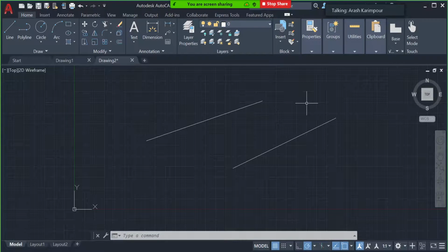How does it help me? It helps me change the properties of that layer altogether. For example, if I want to change the color of my walls without changing any other colors, I can go to the layer that contains the walls and say, only change the color in this layer and leave the rest of the layers as they are. Or if I want to make sure that my doors stay the way they are and are not changed, I can freeze the layer that contains my door drawing and say, freeze that layer, don't let me make any changes in it.